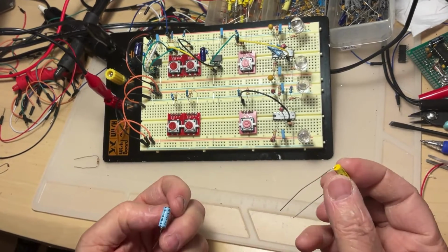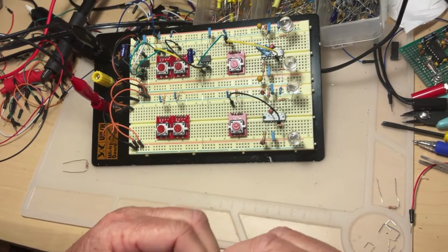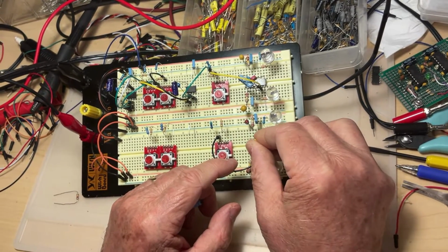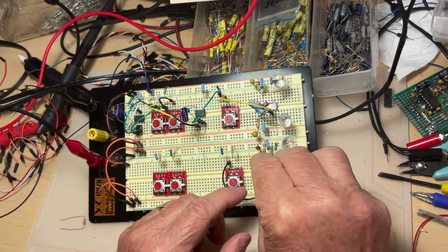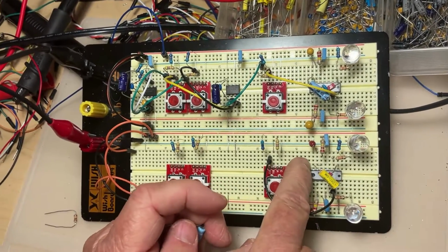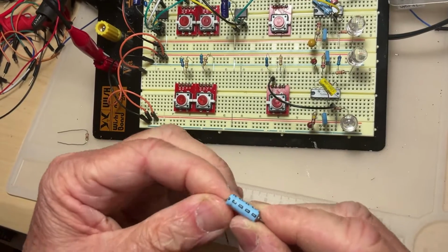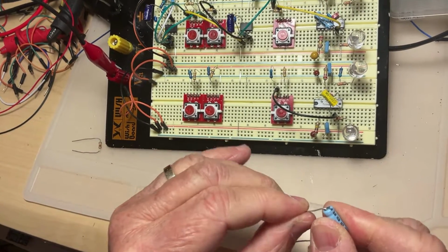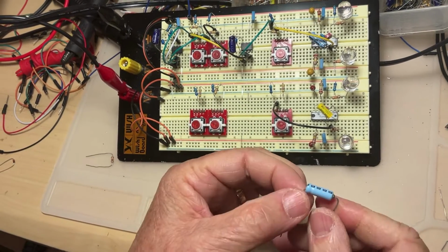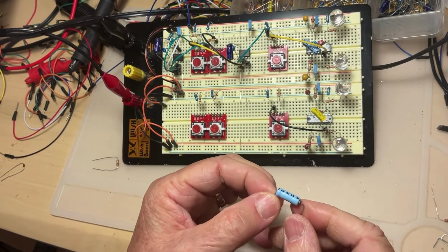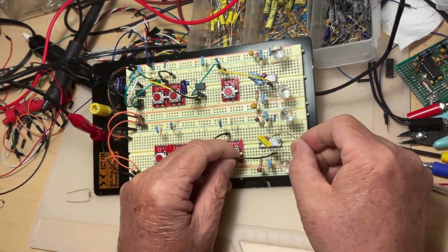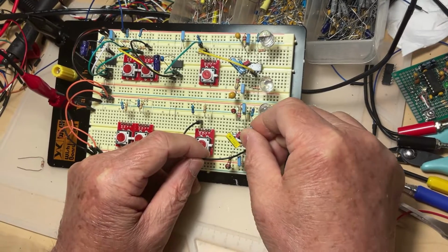One of them is a small capacitor. This is 10 nano. So it can be anything between 1 and 100 nanofarads. It's between pin 7 and pin 14, as you can see. 7 being the ground, 14 being the positive. And the second capacitor, to prevent the propagation for lower frequencies, which is an electrolytic capacitor, I'm going to use anything between 2.2 and 10 microfarad. This is 4.7. So I'm going to do the same thing in parallel with the other capacitor.